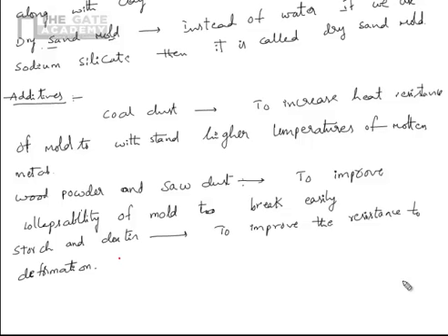So these are the mold materials which are necessary to add along with sand. Water and clay are essential, you need to add them. There is another type of mold besides sand molds. For metal molds you don't need to add anything. Metal molds are used for very special purposes, very rarely, and those are different types of casting. If you use metal molds, those are called die castings. That is discussed later, but first the more important one is sand molds.